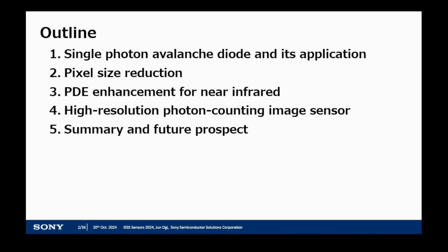After a brief introduction of the SPAD and its application, I will introduce three key technologies for the SPAD applications. One is the pixel size reduction, another is PDE enhancement for near-infrared, and the other is high-resolution photon-counting SPAD sensor. Finally, I will summarize my talk and show the future prospect.